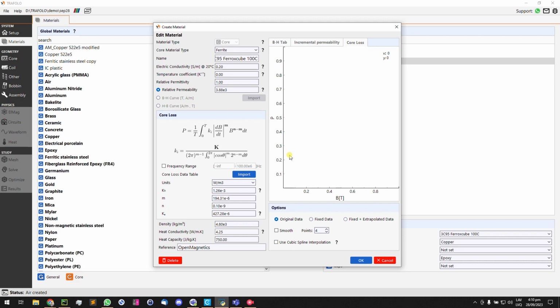What we cannot treat now is anisotropy in material permeability. So for example, this is very often in cold rolled electrical steel. So you have permeabilities different depending on the rolling direction. So with this software, we cannot do that, but we can add that manually to the model. So once you create the model, you can add manually different anisotropic permeabilities.